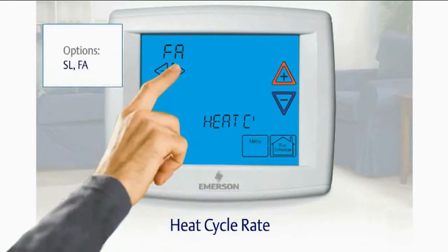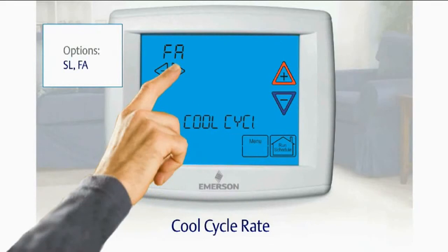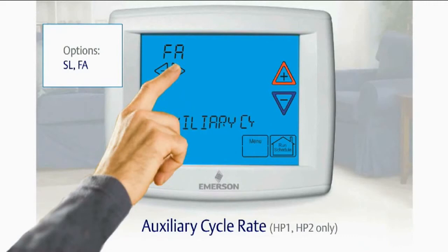Are you going to energize in heating, or are you going to energize in cooling for the reversing valve? Menu items 4, 5, and 6 deal with cycle rates, the number of times the equipment will turn on and off in an hour. If you select fast, you will have shorter cycles per hour and much tighter control of temperature. If you select slow, you will have fewer cycles per hour and longer run times, typically used on an air conditioner or heat pump in air conditioning to dehumidify better.